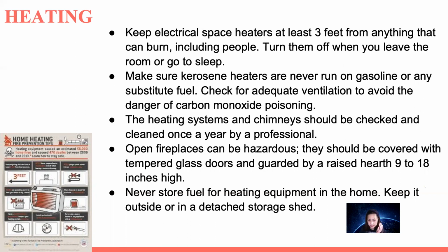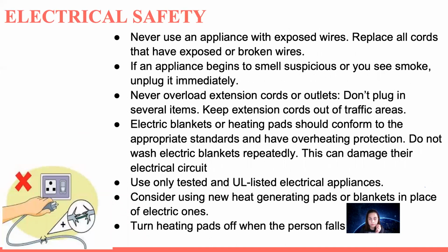The heating system and the chimneys should be checked and cleaned once a year, because if there's a buildup of dust particles or any fire-creating material, it can create fire. Then, open fireplaces can be hazardous. They should be covered with tempered glass doors. Then never store fuel for heating equipment in the home. Never use an appliance with exposed wire.